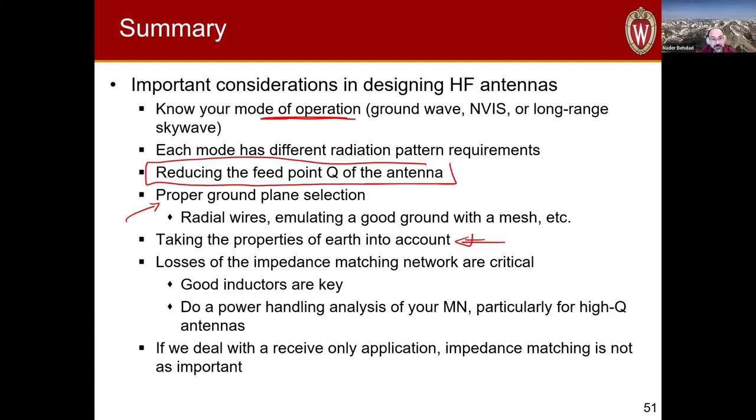This is extremely important. And then also your impedance matching networks. The losses in these impedance matching networks are important. If you're a designer and you want to invest your time in improving something, designing good inductors is really the key, and making sure that the power handling analysis has been done, that you're using components that are rated for the power levels that you're dealing with.